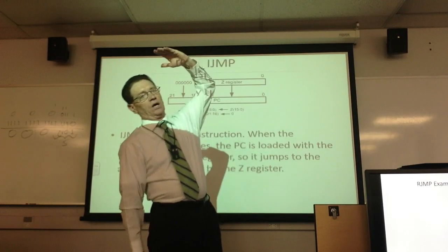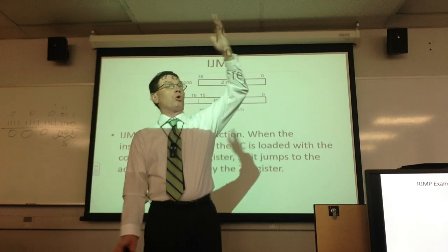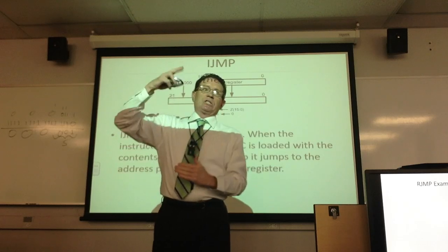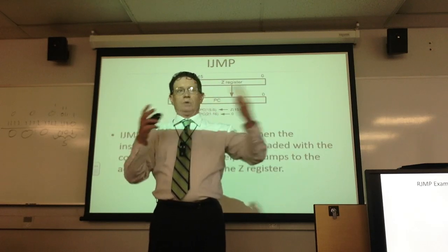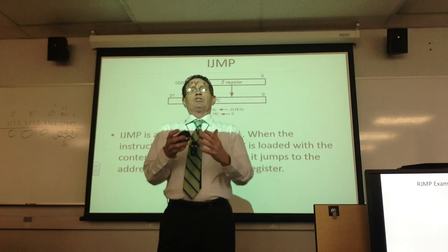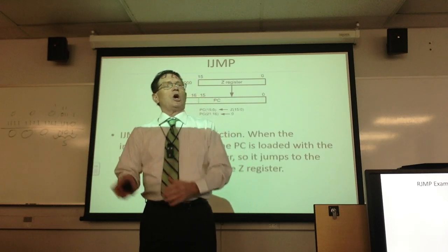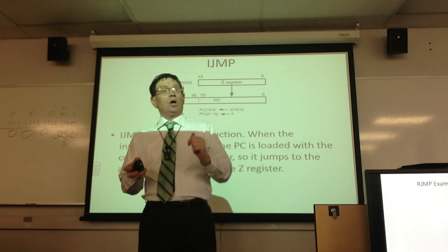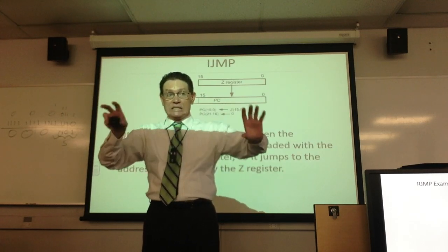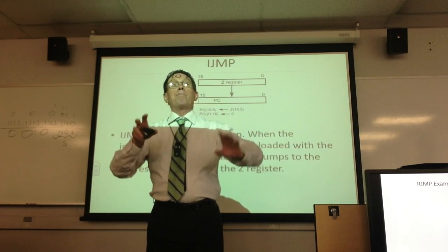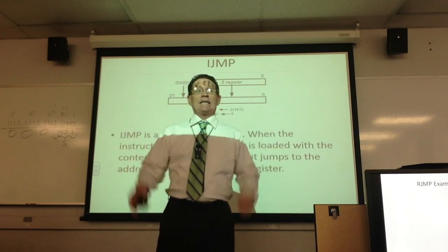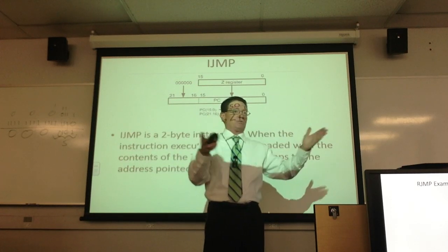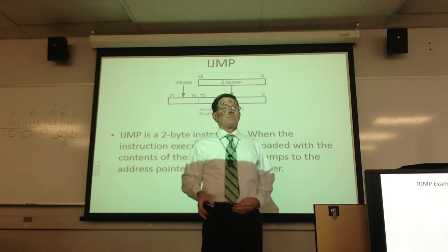If I've got a really large amount of flash, 4 meg, big time, I can't address that with 16 bits. I now have to go to 22-bit addressing. The Z register only holds 16 bits. There's something called the RAMPZ. If you look in my chapter 2 slides, you'll see I mentioned this RAMPZ, and that takes the Z register and also adds on another register that gives me the other 8 bits of addressing. What register is this one?